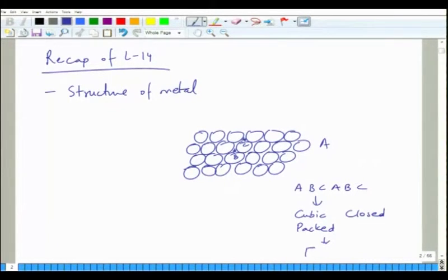This can be described by an FCC lattice with a motif at 0, 0, 0. So this is ABC, ABC packing. If you pack in an AB, AB stacking sequence, where you put the next layer at B, then the next layer again comes back on A. You don't have to necessarily go to C, which is the alternation of ABC, ABC type of packing, but both are close packed structures. This is called hexagonal close packed structure.